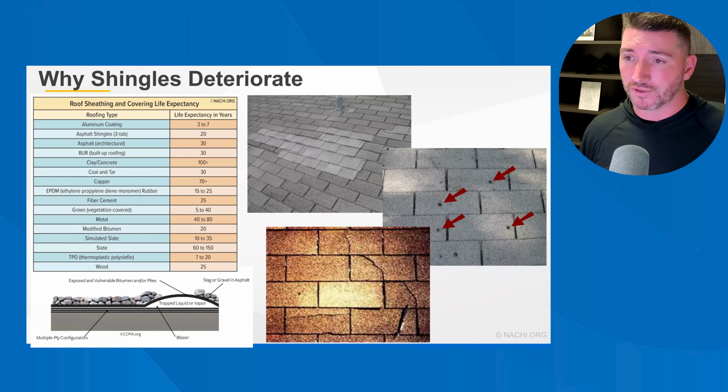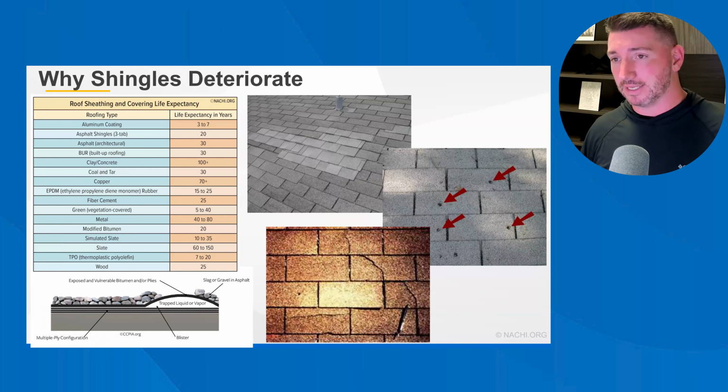All roofs that are poorly ventilated can overheat and degrade a little bit faster, but blistering is exacerbated and manifested by maybe poor ventilation or just being in a hotter climate. But the cause of it specifically is that there's a trapped volatile gas in the asphalt during the manufacturing process. That gas expands in heat.